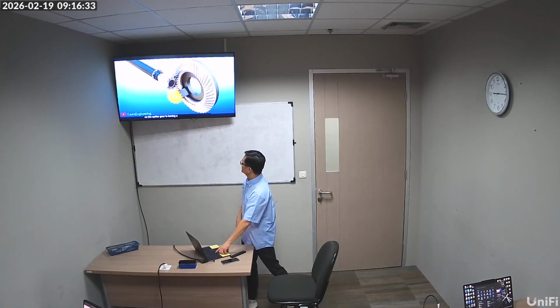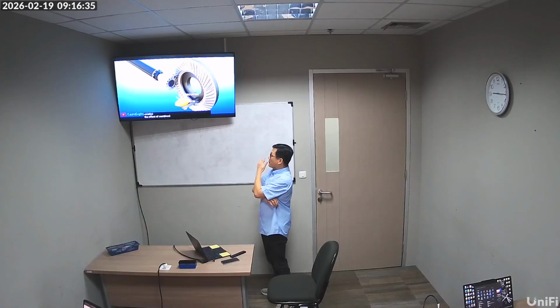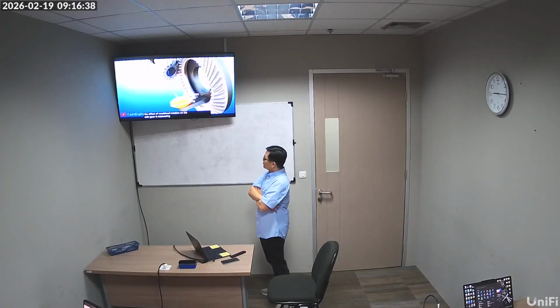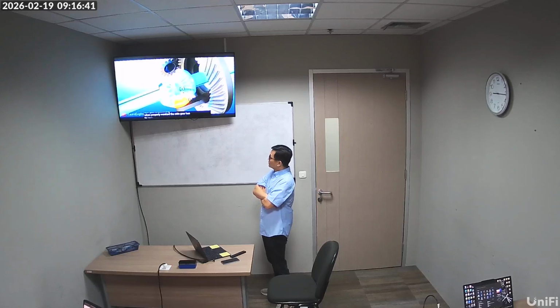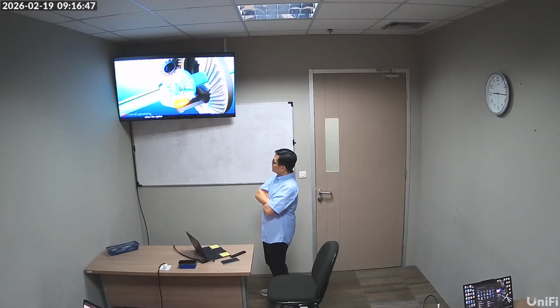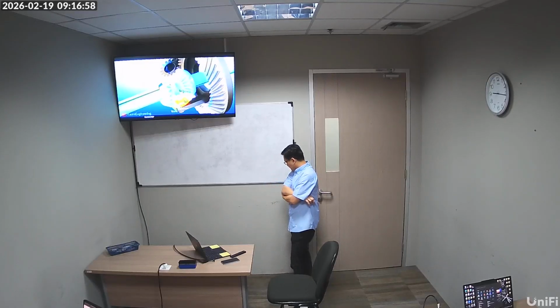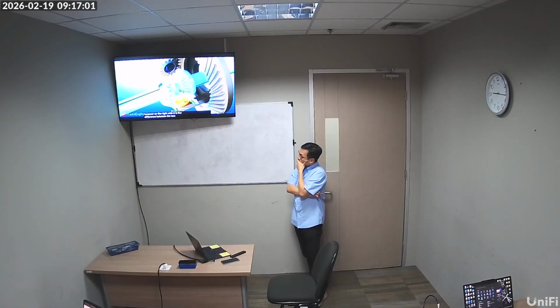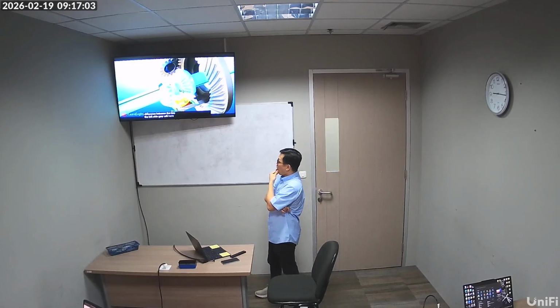So the spider gear is having a combined rotation. The effect of combined rotation on the side gear is interesting. When properly meshed, the side gear has to have the same peripheral velocity as the spider gear. When the spider gear is spinning and rotating, the peripheral velocity at the left side of the spider gear is the sum of spinning and rotational velocity. However, on the right side, it is the difference between the two. The left side gear will have higher speed compared to the right side gear, which is how the differential manages to turn left and right wheels at different speeds.